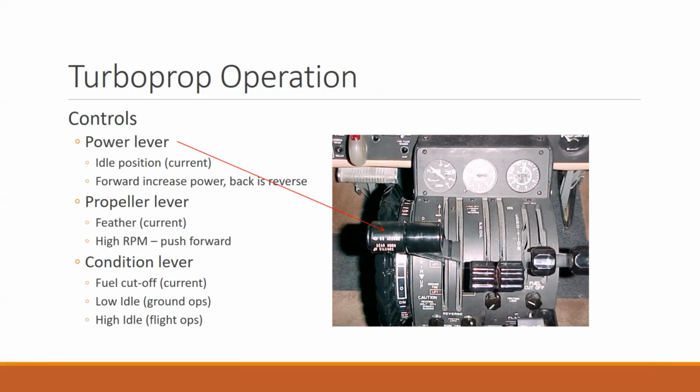And once the blades are in a reverse direction, as you continue to pull back, it actually starts to throttle the engine up. It does the same thing as if you'd push the levers forward. It starts to add more fuel to the fuel control. And just like thrust in beta range going forward, the reverse blade angle and the power are both controlled by those thrust levers when they're in reverse.